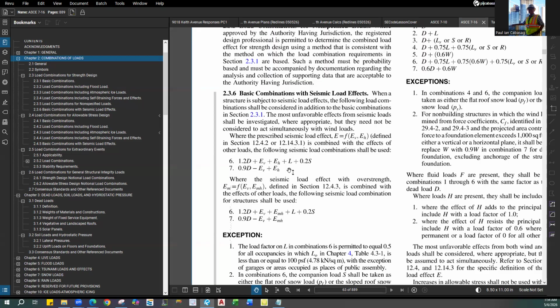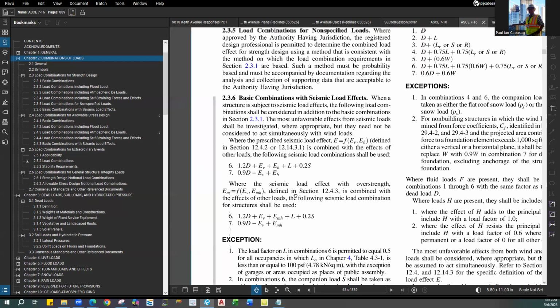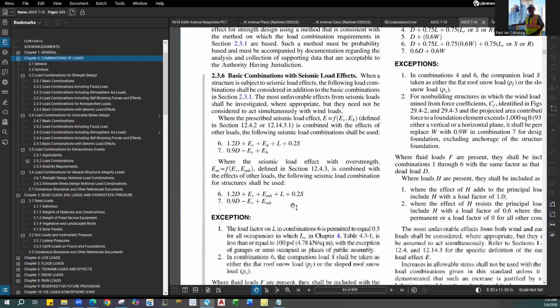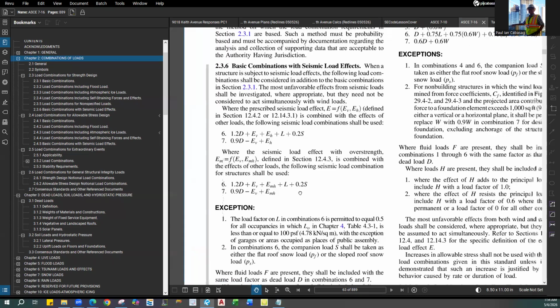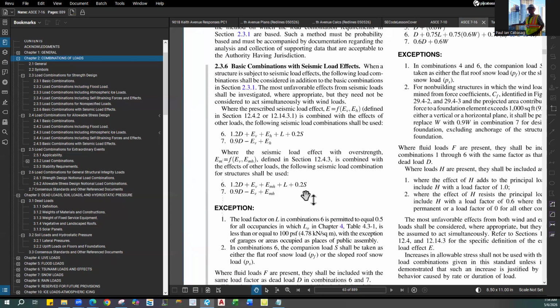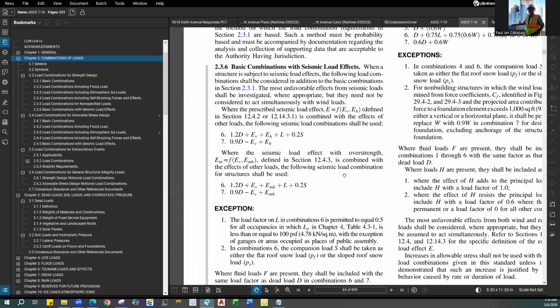A shear wall has overturning moments, and at the ends you have the boundary elements, and for those boundary elements you have to consider uplift when there's tension going up. So this is the type of load that you're mostly going to use to design your boundary elements. We'll get to the specifics once we get to the material building loads. Right now we're looking at just the building load.